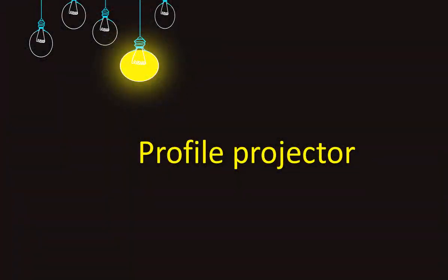The next one is profile projector. Profile projector is an optical device which is used to check the profile of components having special formed surfaces such as gears, screws, and those objects having regular or irregular profile. It is also known as optical projector. It is a highly sophisticated and versatile optical instrument which is designed as per international standards.